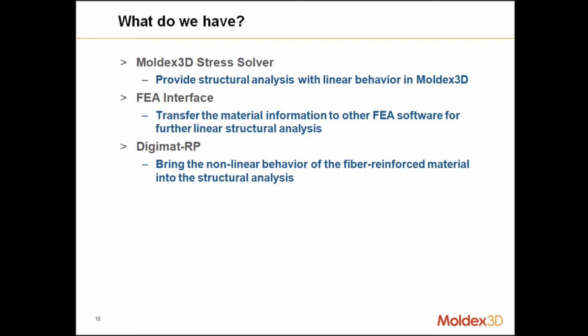Now this slide is showing what we can provide to the customer to have a better structural simulation result. First, for the normal user, if they don't have any structural software, they can just use the Moldex3D stress solver to do the very basic simulation, to make some fixed boundary and some force loading on a certain area to make a static structural simulation.